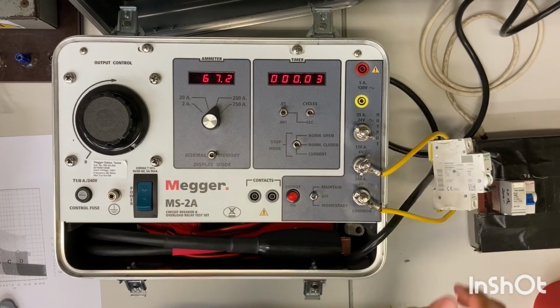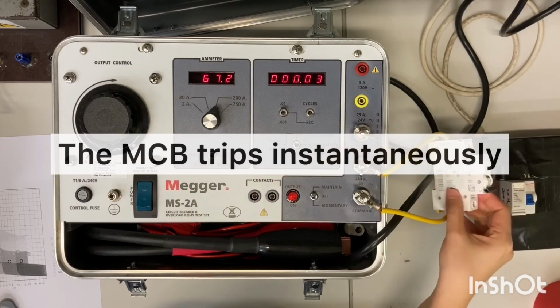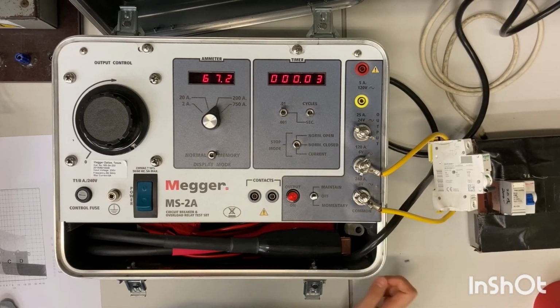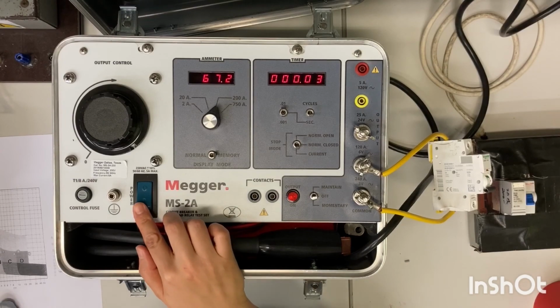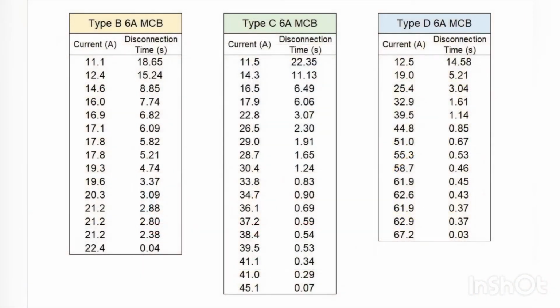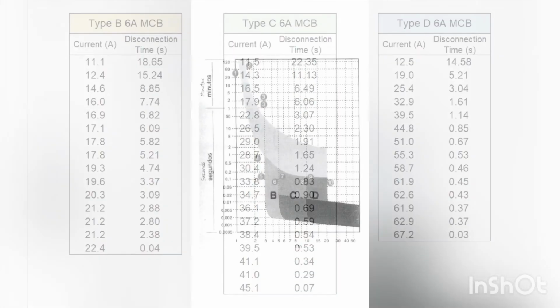The MCB has just tripped instantaneously. So this is the last set of data for the type D MCB. These three tables summarize all the measurement data for the type B, type C, and type D MCB. You may plot these data onto the graph to see if they comply with the British standard.